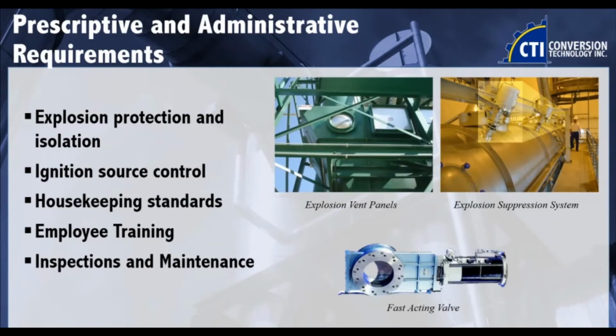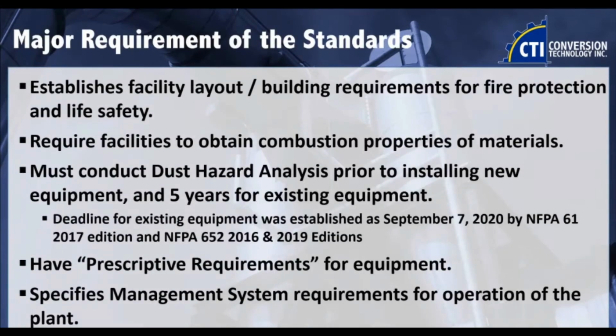So prescriptive requirements in the standard will tell you, you have a bucket elevator, it needs to be protected according to these notations. The protection needs to meet these requirements. It kind of prescribes you, it tells you what to do, how to do it, when to do it. But obviously within your DHA and management practices, you can kind of make your own facility-specific, company-specific version of that, as long as it is at least as safe as what's described in the standard.